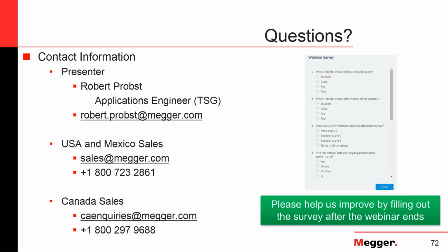And the other thing is, since it's a low voltage test, the interruption is done at the fault current, but not at full voltage. And that changes the properties of the arc. So it's not an interruption under full stress.